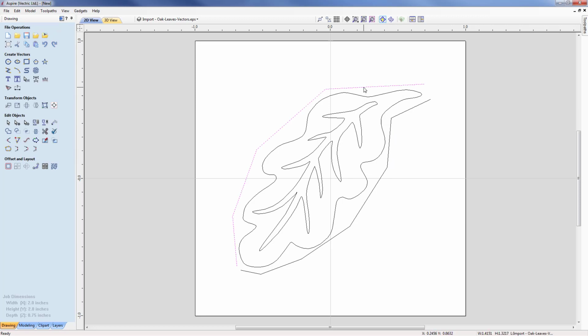So if we come into selecting the first one then and go into the node editing mode, we can see that we've got 3 points that we need to smooth. And I can do that by right mouse key over the individual point and saying smooth point, or similarly I can go over the top of the point and hit S, and I'll do the same for the final point. I will just tweak the tangency in and out of the first and last points to make it nice and smooth, and then come across to the second vector, and we've got 1, 2, 3, 4, 5 points that I